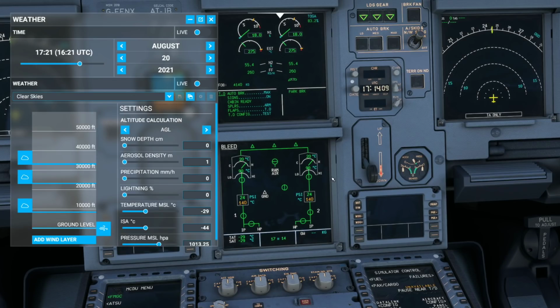So this nice 200 degrees Celsius air is coming out, and it's heating up the leading edge of your wing. So it's obviously a cause for concern when this temperature is not where it needs to be. So this is when you would get a little bit of an ECAM memo. But again, you can see the effects of the modeling of the adiabatic heating, because if I bring the thrust up again, you will start seeing the temperature start to rise a little bit. And you can actually see the packs start to self-regulate and close their valve just a little bit so that they can maintain that 20 degrees Celsius output.